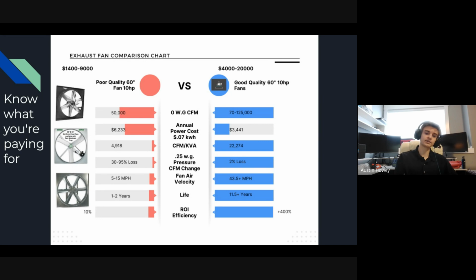If you look at the fan on the left, it's some heavy duty. I've seen, for example, some of the crypto container pods with these really heavy duty cabinet fans, and they have these giant tube axial, all-weld aluminum blades. They're all welded around the hub, and they're really good for static pressure, but they're extremely inefficient on the CFM side, where you're going to be using a 5 horsepower motor for 15,000 CFM.